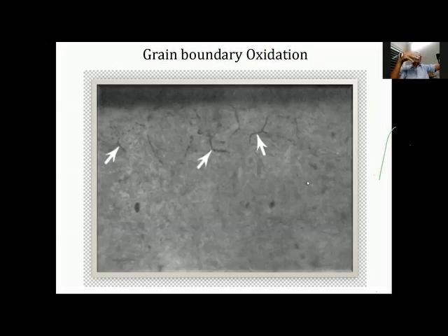Subsequently, of course, it will also be subjected to vacuum degassing and the final deoxidation by either aluminum or vanadium, depending on the type of grade that you are talking of. Under this condition, the steel becomes fine grained and the oxygen content is reduced to a great extent, reducing the oxide inclusions in the steel.